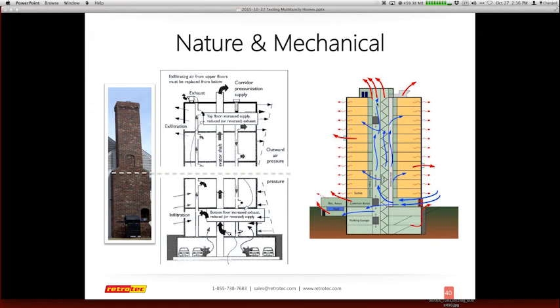The other one that you can do, instead of the total leakage, is dealing with individual units of leakage from unit to unit, or even just a unit by itself. You also want to determine if it's leaking to the unit to the left or the right or top and bottom. That gives you an indication of how these units are connected together, which the large total building test does not do. The large building test just tells me if my exterior skin air barrier is working correctly or has some flaws. It doesn't tell me if I'm leaking floor to floor or unit to unit.